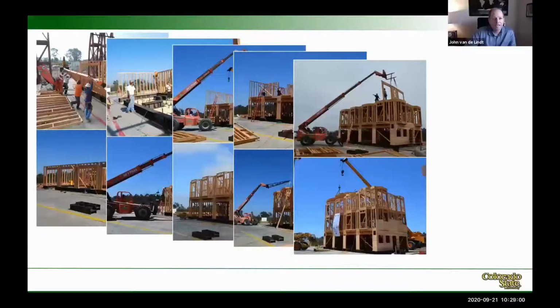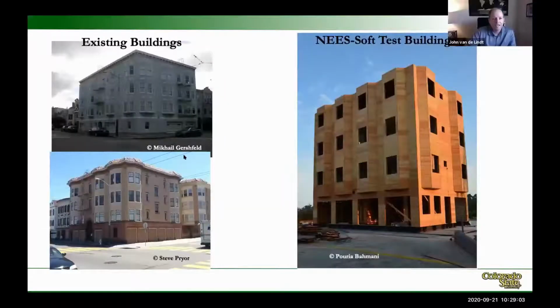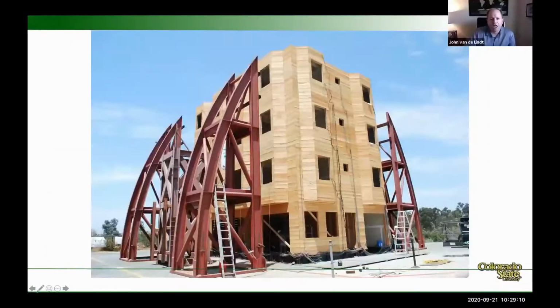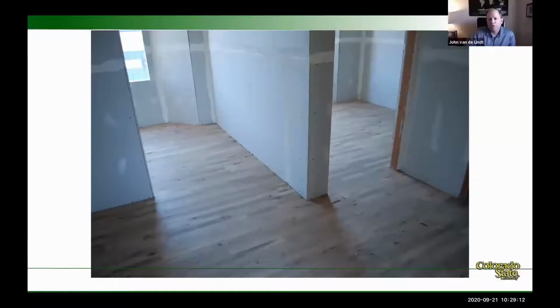Now, one of the unique things, and these are decisions that you have to make as you go through, was these buildings were built so far back that there really wasn't any steel connection hardware available, and so it was essentially wooden nails. And so this was the only building I've ever tested where I had a finished floor put in, and that was because it actually provided stiffness and strength to transfer load throughout.